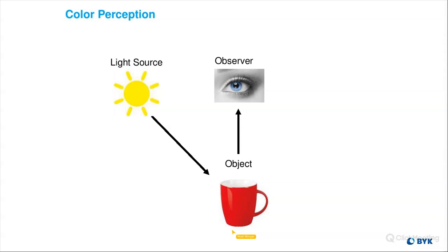But if you tilt it a little bit, or set it up in a way where it's 45-0, where your light's coming from 45 and you're looking directly overhead, or your light's right overhead and you're looking from 45 degrees, because you're not getting that specular reflection right into your eyes, that's how you're able to see the color. So 45-0 is similar to this setup here, whereas a sphere is very different. Your measurements aren't going to correlate.